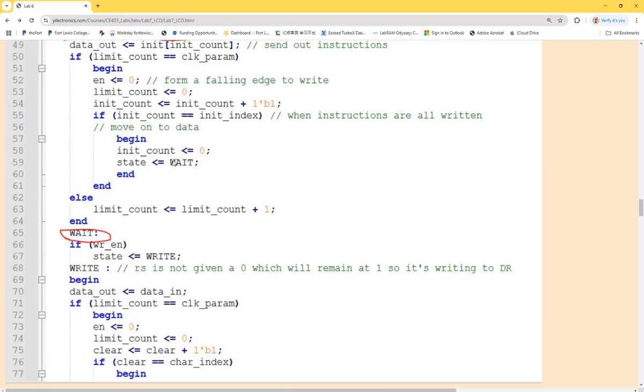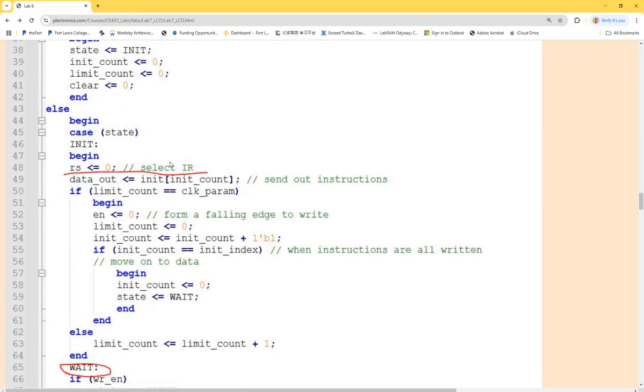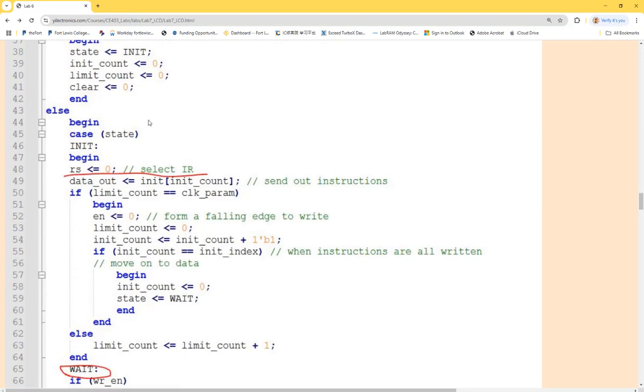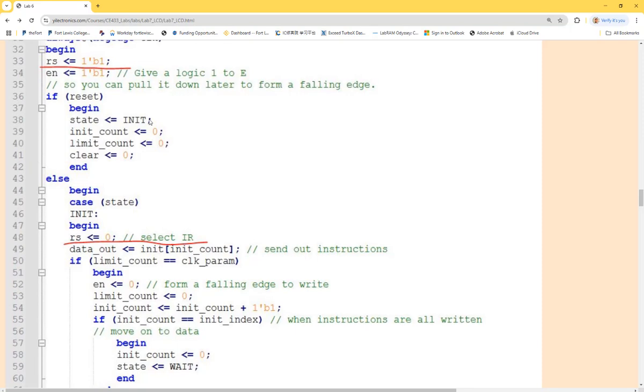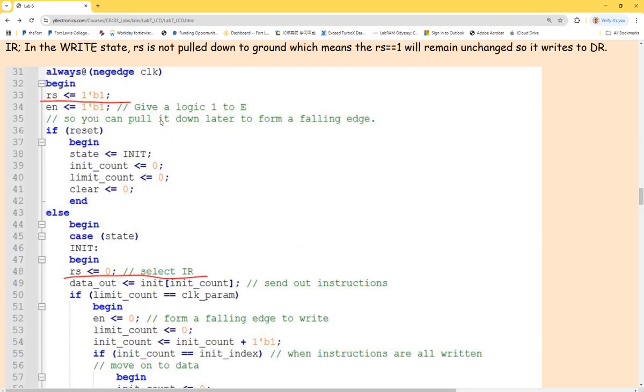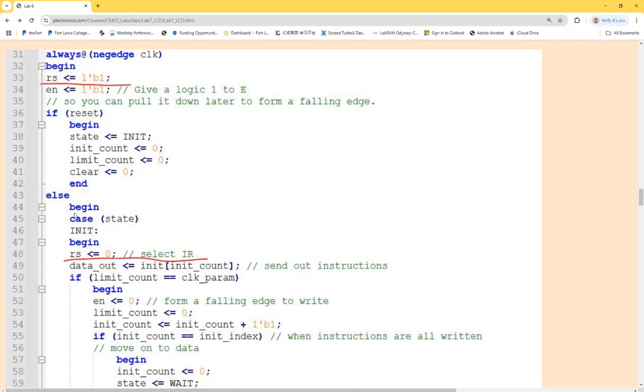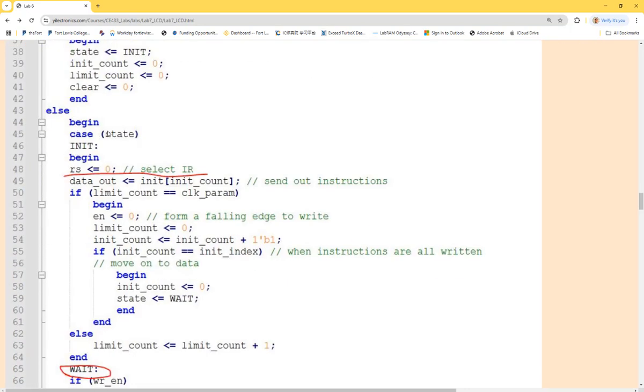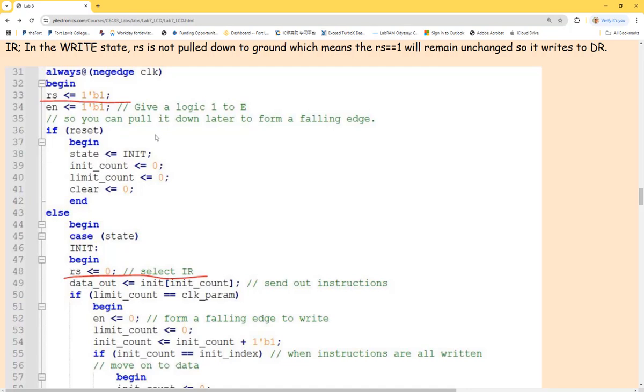Actually, does the state only execute once? The state is just a state, it's just a byte. What do you mean by execute once? Like, it will happen once and then at every clock cycle it won't matter anymore because we already did the case state? No, every time it comes to the case state and tries to see what the current state is, right? And then directly jumps to that state. What is state? State is just a byte, just a variable.